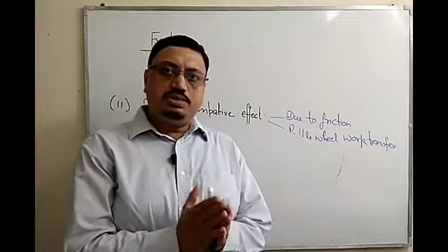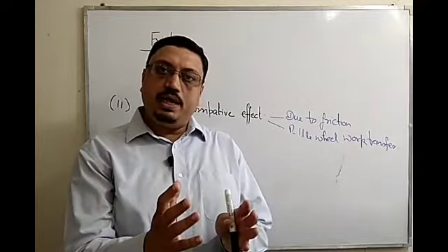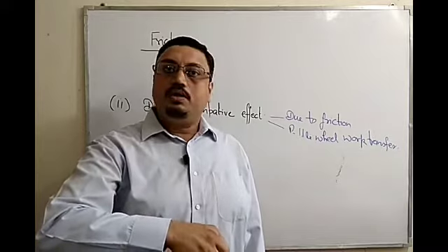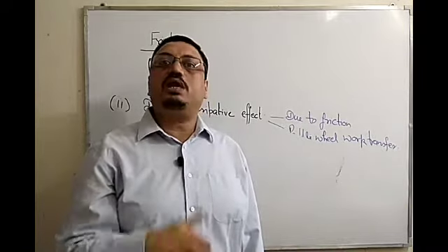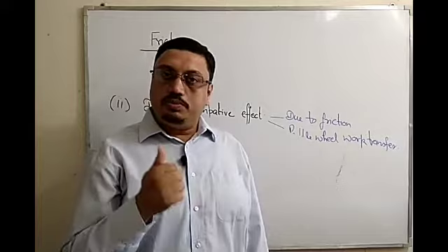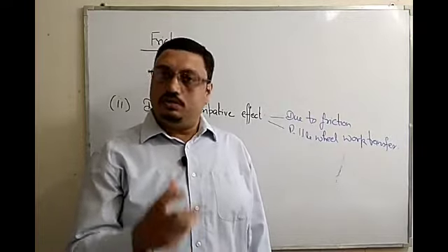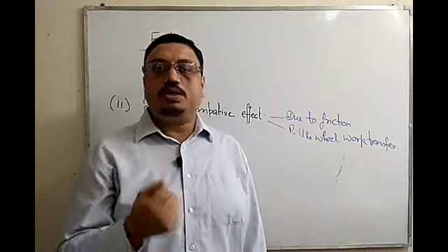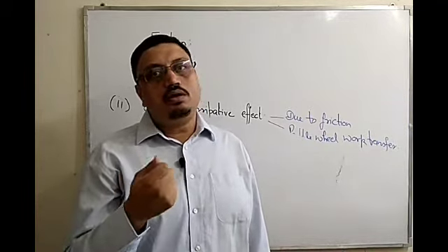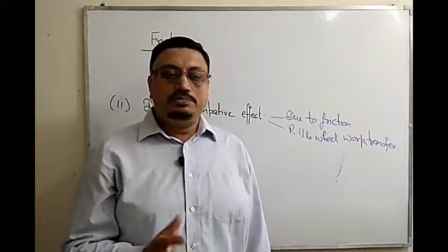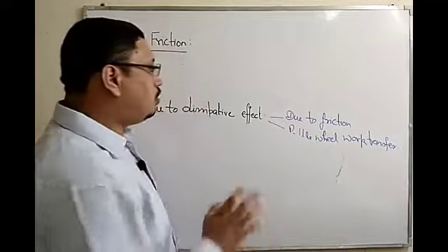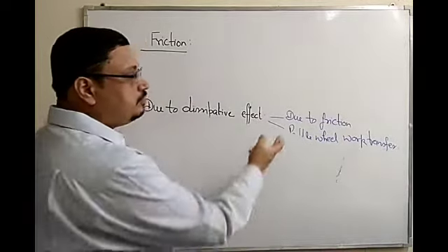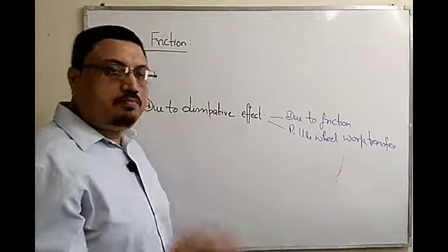Now, is this process reversible? Can we supply the energy stored in the material of the brake shoe to the rim in the reverse direction so that this wheel will start moving? No, it is not possible. So friction is also one of the causes of irreversibility. This vehicle has stopped because of the friction between the brake shoe and the wheel, right? So friction is a cause of irreversibility, and this friction cannot be avoided. So there is irreversibility in the process.